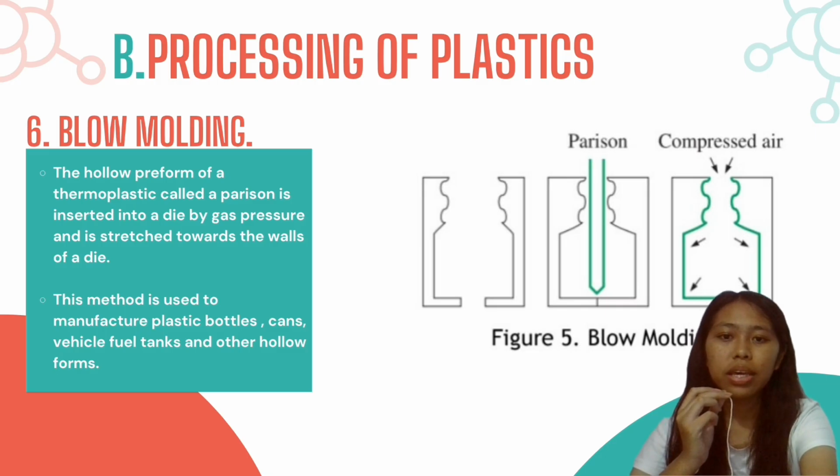In blow molding, imagine you're inflating a balloon, but instead of air forming a random shape, the balloon is inside the mold. The plastic tube, which we call the parison, is softened first.